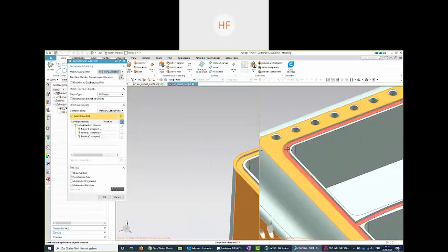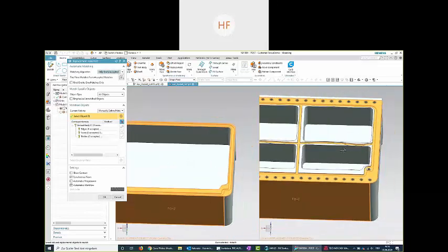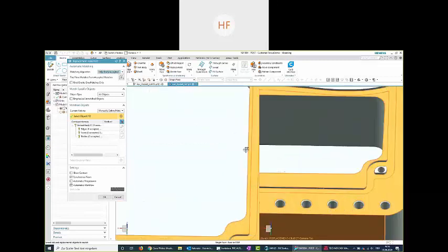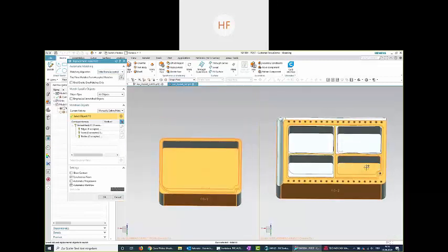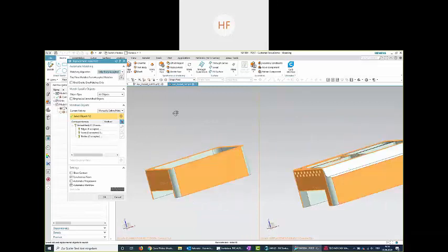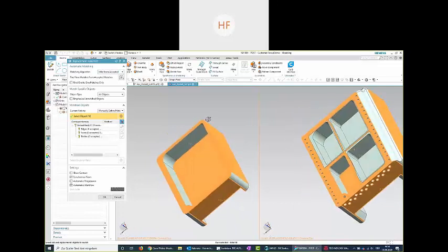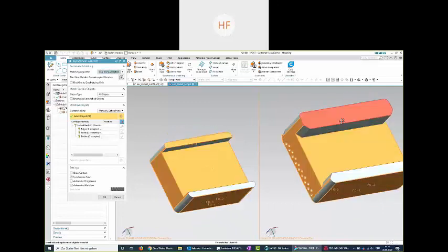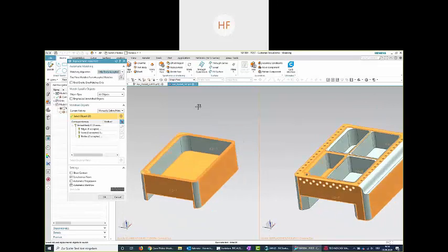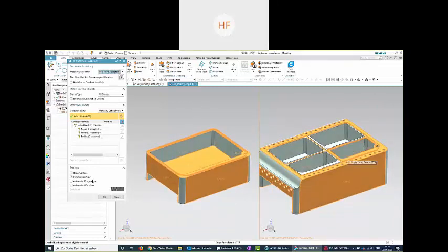What I'm doing now is selecting, or usually creating, some basic faces on the part. For instance, the extreme faces, the longest, the highest, the widest faces will be replaced by me. And by doing so, I am reassigning the intelligence from the old part to the new one.